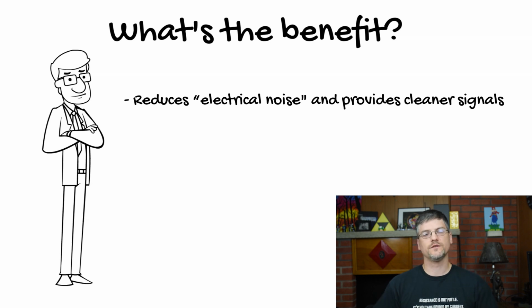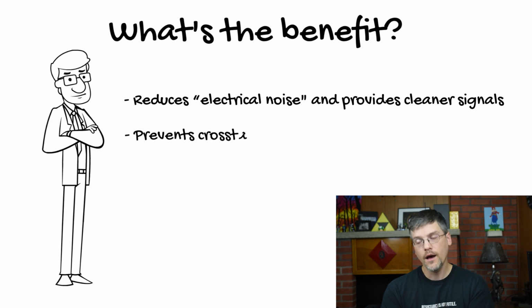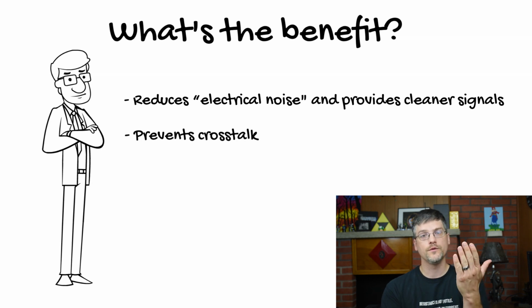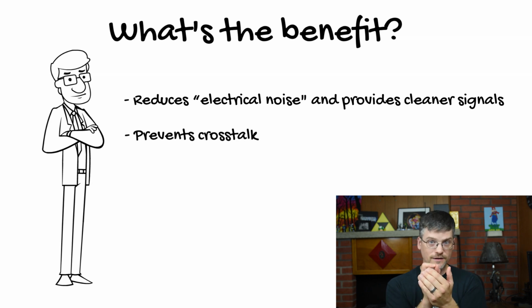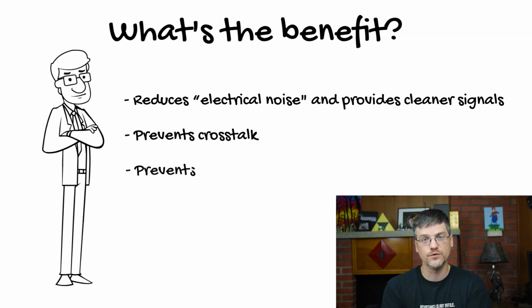Analog and digital signals will sometimes produce crosstalk between one another, which is bad. Ways that we can prevent this from happening is either via fencing, which is surrounding the analog circuitry or your digital circuitry with vias connected to ground, or you can have an analog ground plane and a digital ground plane, and they're connected with a thin wire. This helps prevent crosstalk between those two types of circuits.